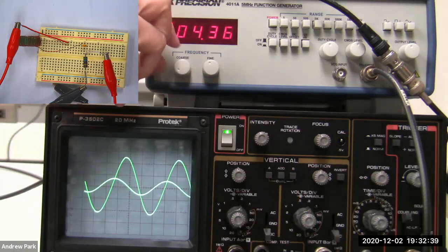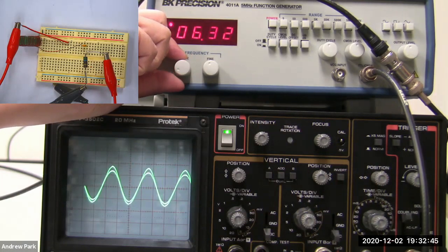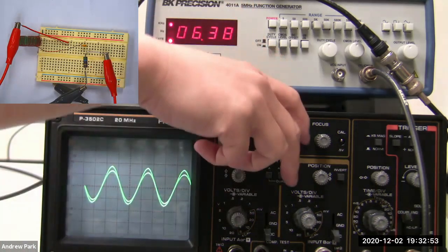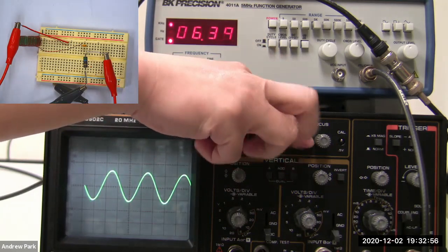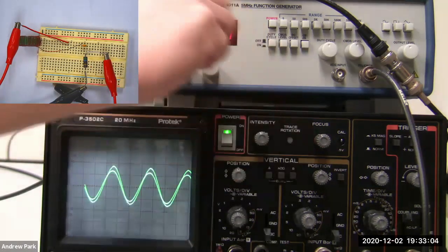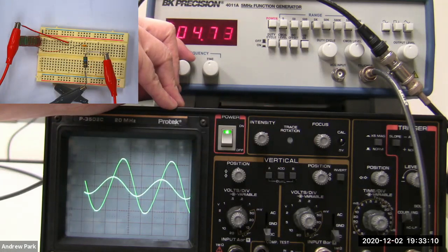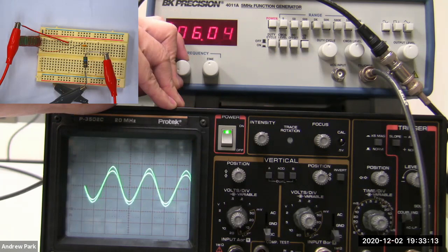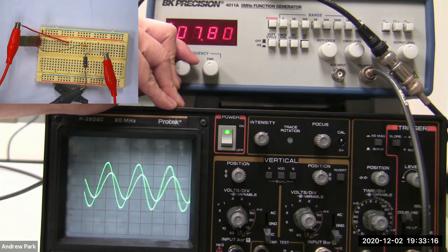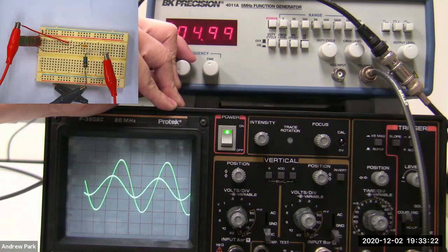And now as I increase the frequency here, there's a point where the voltage and current are in sync. They have the same phase. And that's also where, let me turn off the input voltage so that there's no more voltage. All you're seeing here is the current. And that current goes through the maximum here. And the point where it goes through the maximum is where they are in sync. Lower than that frequency, current was, I don't know, leading the voltage or whatever. And after that frequency, the current is lagging the voltage. I always get those mixed up, leading and lagging. So I could have said it the other way around.